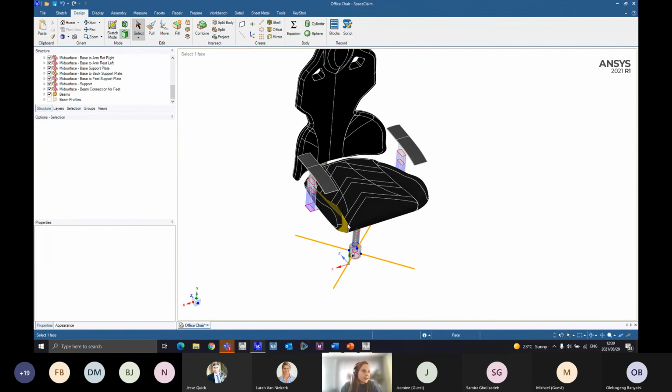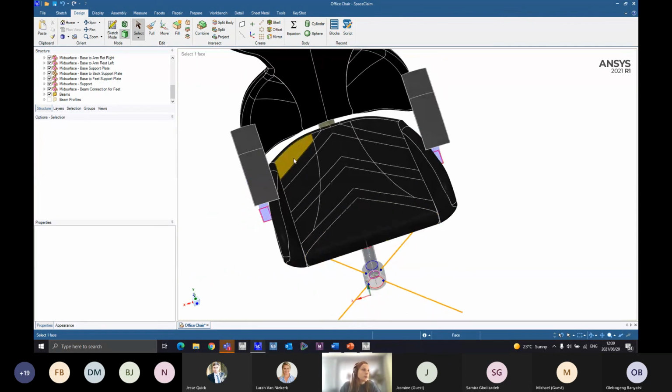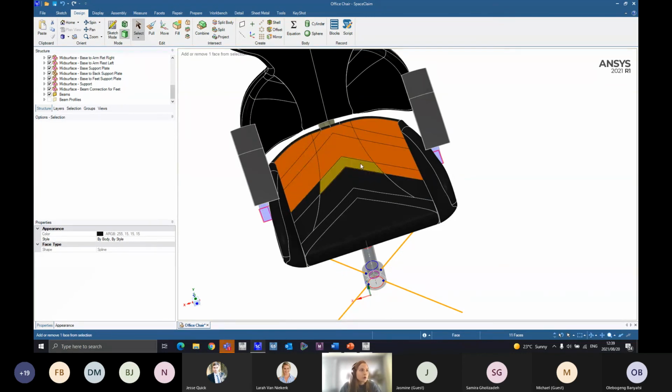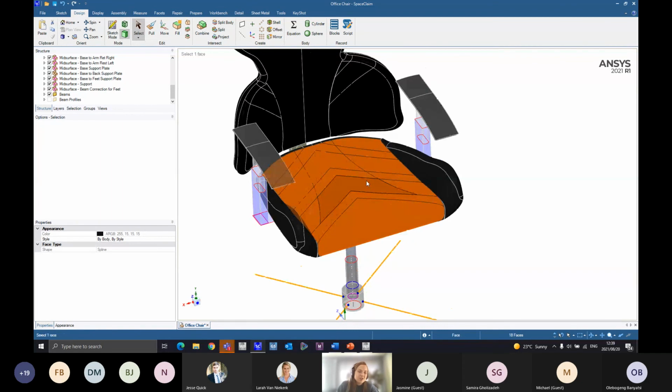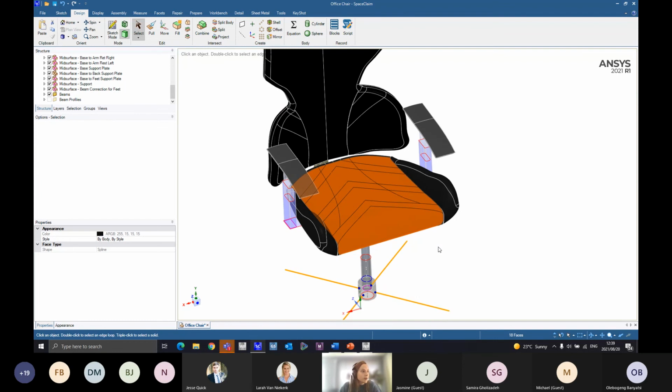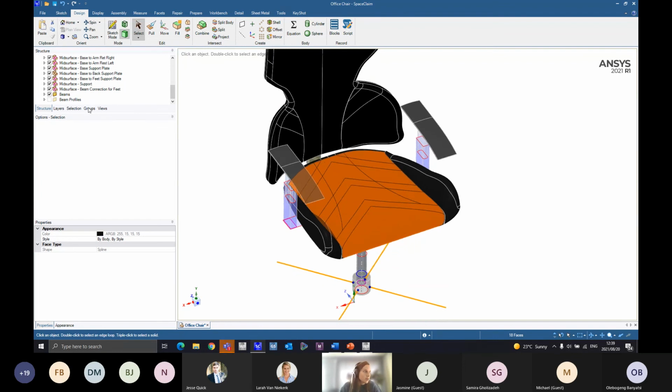So, for this case, I'd probably like to scope a mass or a remote mass or a weight or a force or whatever to these faces over here. So as I mentioned earlier, you can merge all of those faces as well, but I'm not going to demonstrate that as it takes quite a bit of time, but I will actually create a named selection for them.